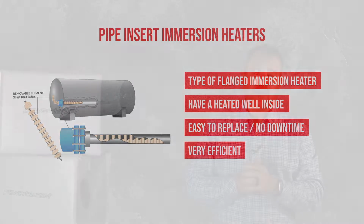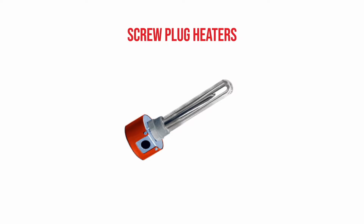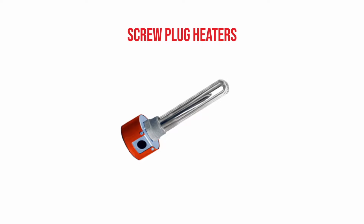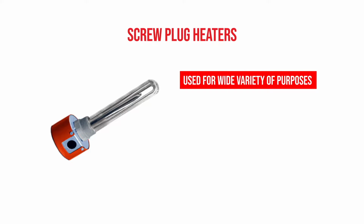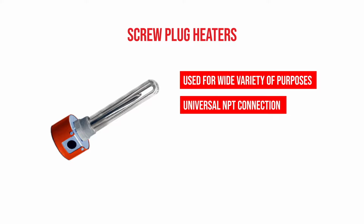And actually, for a lot of tank heating applications, it works a lot better than a screw plug or a flanged immersion heater will. Screw plug heaters are kind of like the duct tape of the immersion heater application industry. They're used for a lot of different things. They can be screwed in by a connection that's called an NPT connection, National Pipe Thread. And so just like on piping that has threads, it is designed to thread only to a certain point, then you can no longer tighten it anymore.